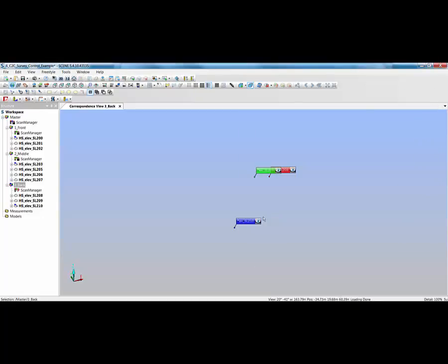The reason for that is that cloud-to-cloud is looking for common constellations or patterning or overlay between scan points. Because the transformation is so wildly different between the positions of those 3 scans, cloud-to-cloud physically won't work. Now, I could either move the 2 scans 0, 9 and 0, 8 down in the correspondence view so they overlap with scan number 10, or I can simply run a top view and then a cloud-to-cloud again, because top view is looking at common vertical surfaces. So it's going to use that to do the rough alignment, and then cloud-to-cloud will work.